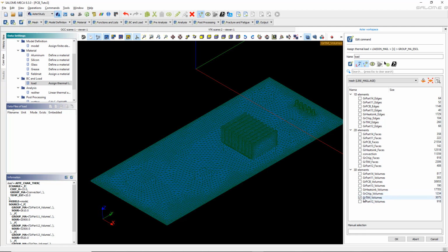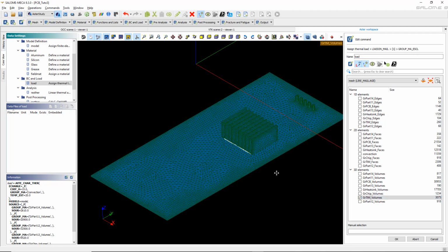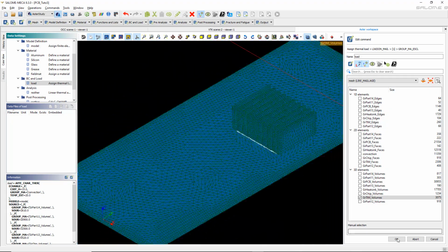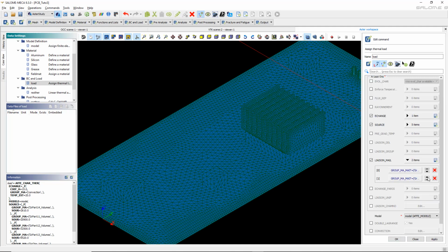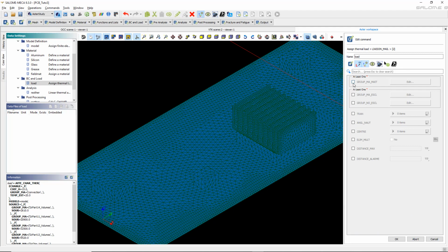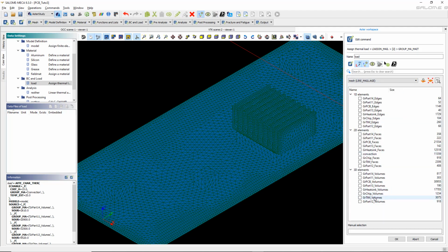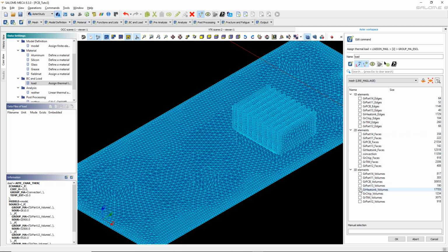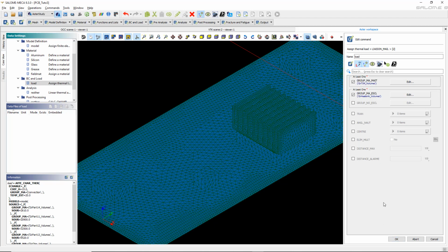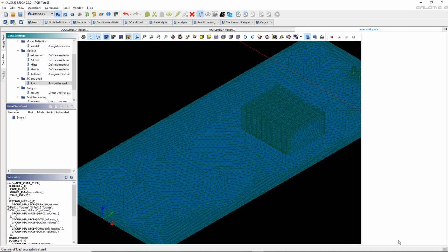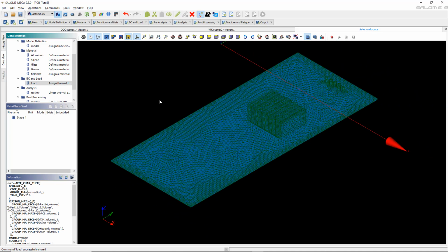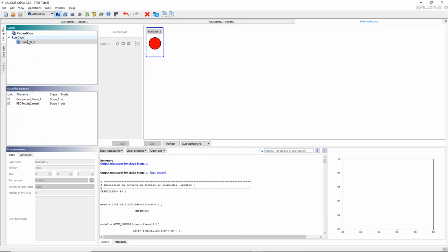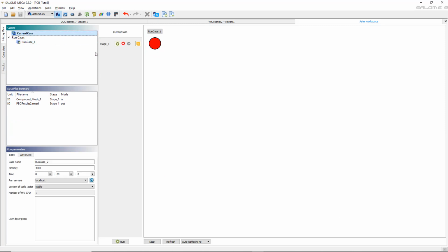So TIM volume. So it's a very slender type of layer that you get here. So I need to create that as well. Okay. And now I need to create another one for between the thermal grease and the heatsink. Okay. So now that this is assigned, and I have nothing else to change, I can go back and launch again the computation. So hoping I didn't do any other mistake this time. So let's go back to current case and let's run that again.